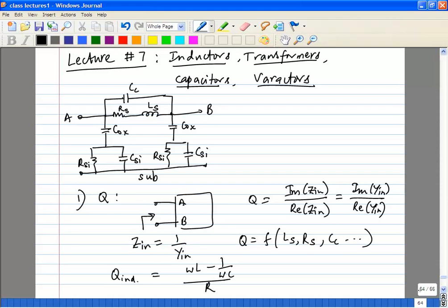It's a bulk substrate, and it has a certain ability to hold a certain amount of charge, so you are representing it as a lumped capacitance. CSI itself will be more a function of your doping levels and so on. It will also be a function of the size of your inductor, because the larger you go, the more substrate there is below your inductor. Is that clear?